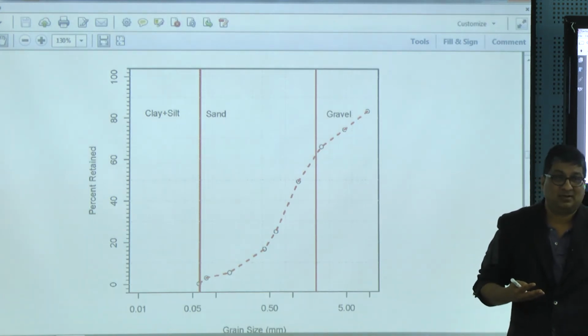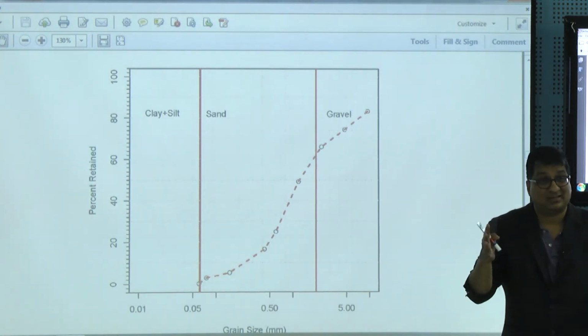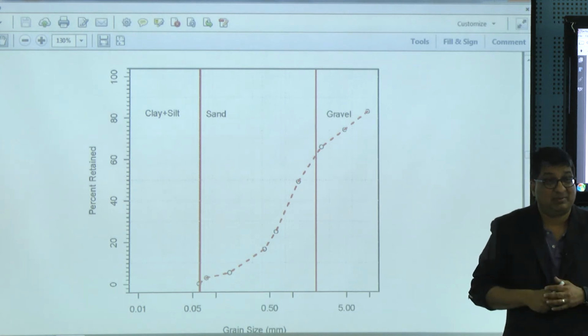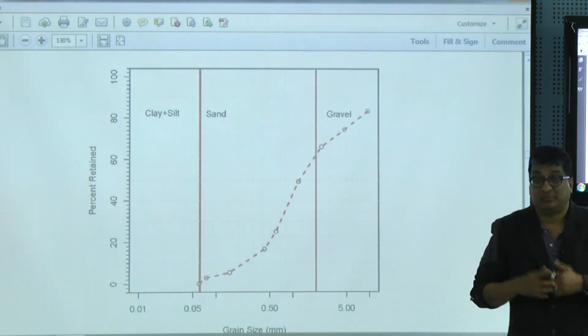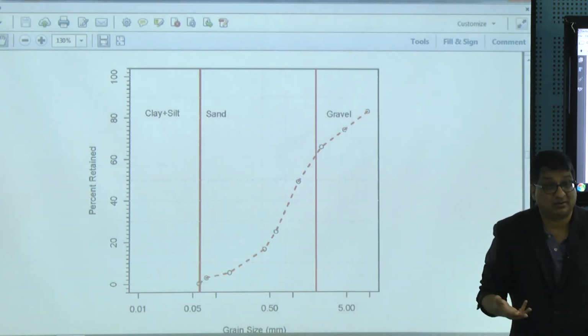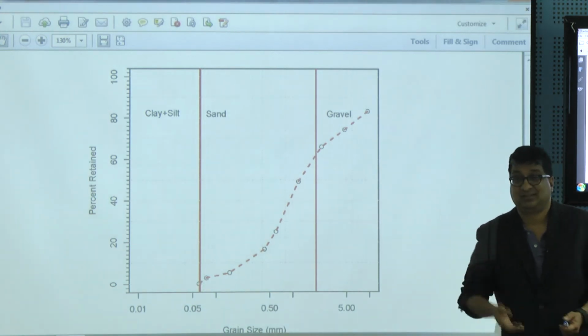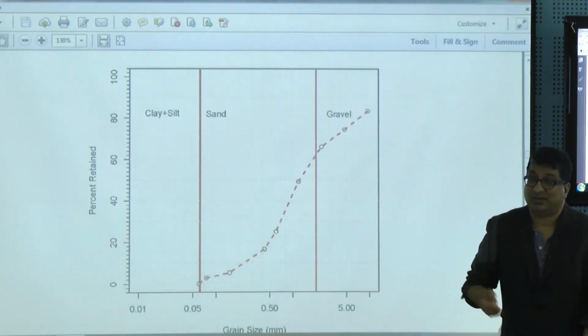So, you will keep on pumping, but the water doesn't come out. You know there is water, but it's not going to. So the sands give you a nice little happy medium in between, where you can pump appreciable amounts of water, but at the same time you're not dewatering the pores very quickly. If you dewater the pores very quickly, it's done. That well can be tossed out. You'll have to put in a new well.